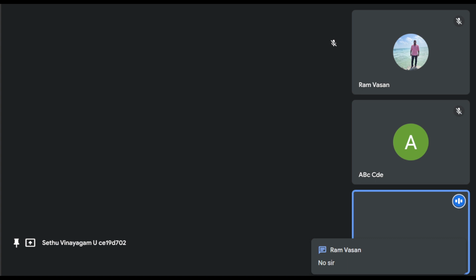T_R is the perception reaction time, PRT. V85 is the 85th percentile approach speed, A is the deceleration rate, and G is the gradient in percentage. The reaction time is given as 1 second, so it is 1 plus 0.28 into what is V85?